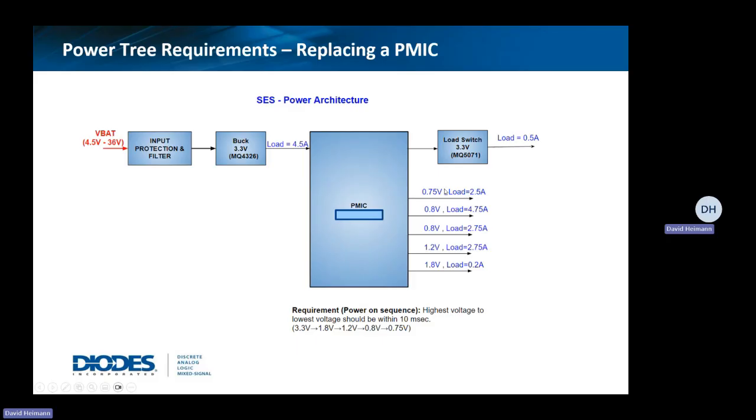I mean, you do lose some of the functionality of the PMIC. In other words, we don't give the ability to automatically throttle the V core voltages and so on. And obviously the software libraries from the processor don't have the drivers to run our discrete design the way they'll run the PMIC.